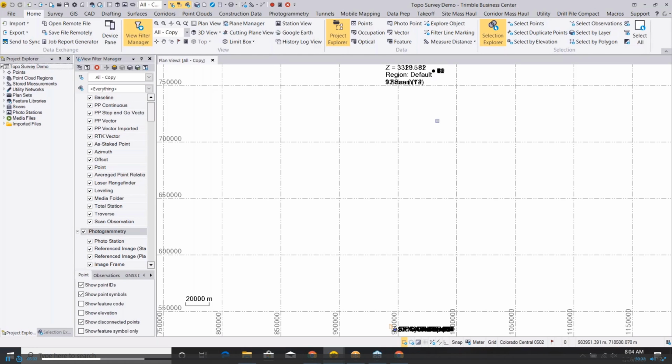So just a little bit of a background, we have SX10 data as well as X7 data. And as you can see, these come in separately, one up north and one down south. The reason being is when importing X7 data into a project, you'll have to geo-reference the data into the correct position because there's a scale factor being applied for all scans that are halfway between where the project is and the origin of the coordinate system. So just a little background information there. And we'll describe to you how to geo-reference and marry those two data sets together here in a little bit.